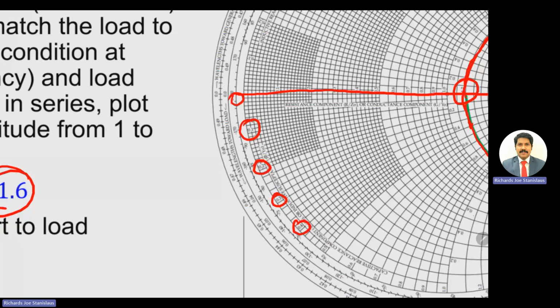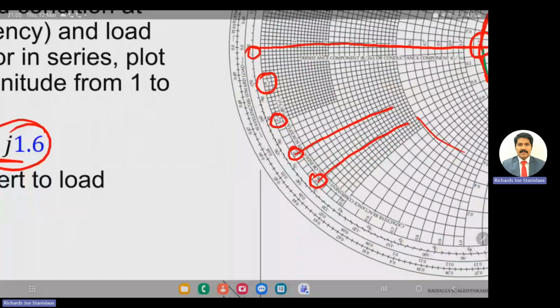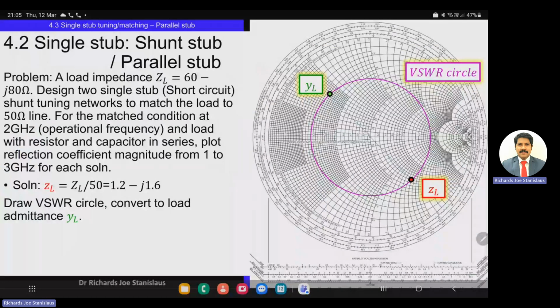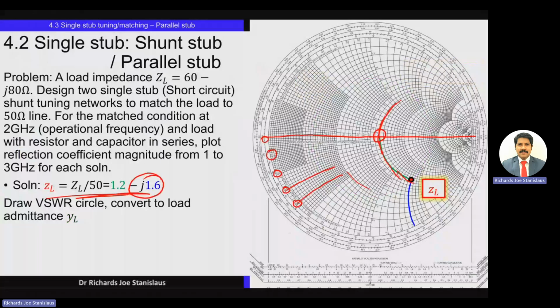You'll be able to see, right? So this circle is the minus 0.3 circle, this circle is the minus 0.4 circle, minus 0.4j, right? So the reactances basically are having the circles below. The negative reactances are all the circles that are below this horizontal line, and all the circles that are above the horizontal line represent the positive reactances, right?